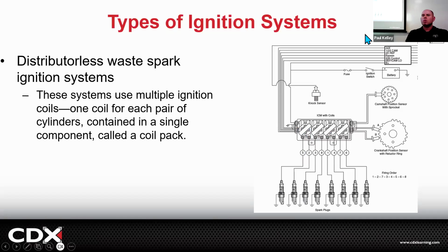Spark them. So ultimately, the ignition control module is controlling when the spark occurs, right? But to know when it should make the spark occur, it needs to look at camshaft and/or crankshaft. Sometimes it looks at both. Sometimes it looks at one. Sometimes it looks at crank, and if crankshaft fails, it looks at cam. Sometimes it looks at cam, and if camshaft fails, it looks at crank to improve the reliability. And also, this can very, very finely adjust the ignition timing.